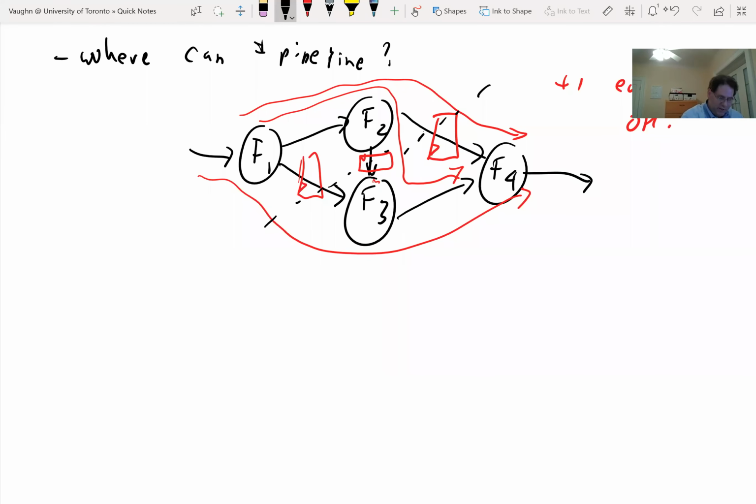And you can see I just did a cut. So this dashed line is a cut, but that disconnects my inputs, which in this case is only 1 input, from my output. So I put a pipeline register everywhere on that cut. It's fine. And basically the edges are always going the same direction across the cut, which is because this is a feed-forward circuit where we can define which side is input and which side is output. This is a shortcut. For this style of circuit, a cut will lead to balanced latency. So it's often an easier way to see how can I pipeline. So kind of an important special case.